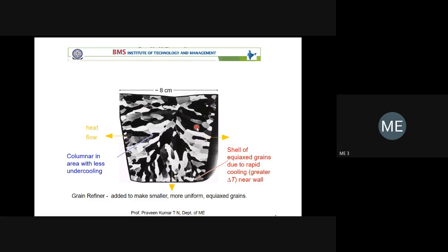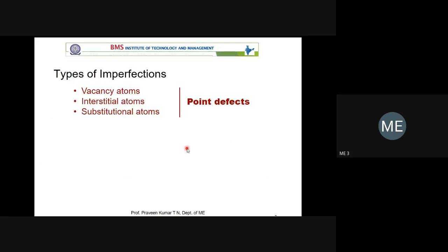And if there are many grains of similar properties and similar structure, those groups of grains having similar properties or similar structure are referred to as a phase. The phase has different physical properties and chemical properties. There are two phases here. I think it is clearly visible. One is the dark phase and one more is the white phase. The dark phase has different properties and the white phase has different properties. If you know that, we can go ahead now.